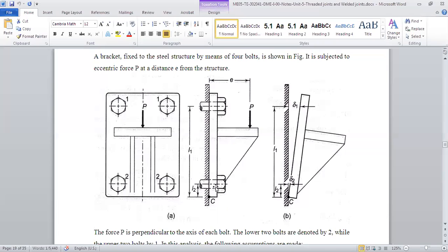So we don't need to worry about the bolts which have a distance less than that. We will design only this bolt, and then obviously the others will be safe because they will have less stress. So we are only worried about the bolt positioned at 1 in this case. Are you getting my point? Because they have the farthest distance, they will have the maximum tensile stress. And since shear stress is common, this bolt will have failure.